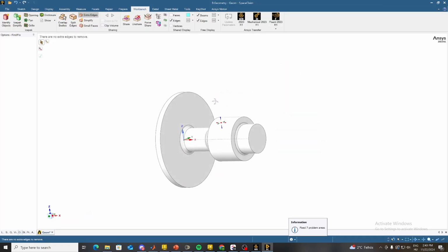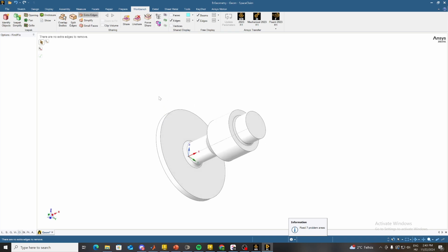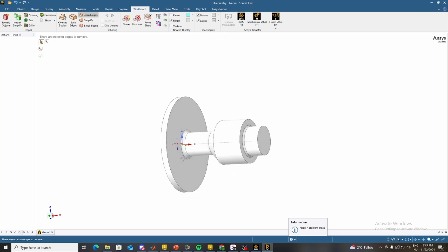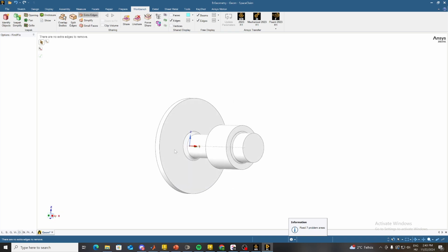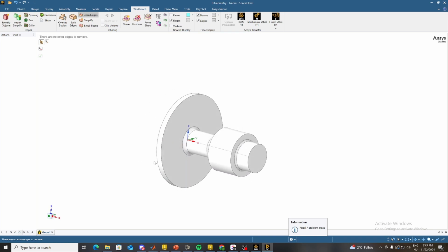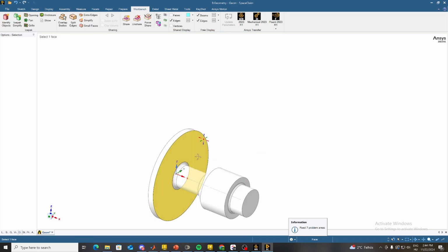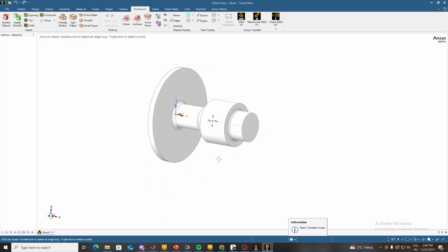Our job now is to think about the boundary conditions and geometry and determine if this can be simulated axisymmetrically. Due to the fact that our pressure is axisymmetric, our constraints are axisymmetric too. We can make this analysis using the 2D axisymmetric simplification. So let's do it. First, we need to create from this geometry a 2D axisymmetric geometry.